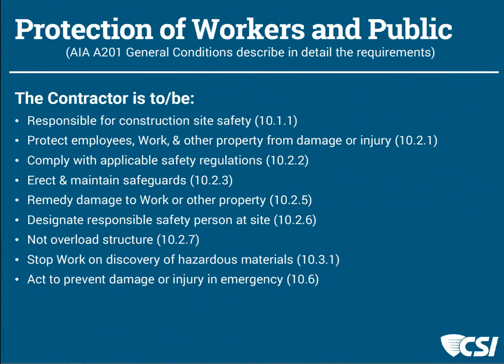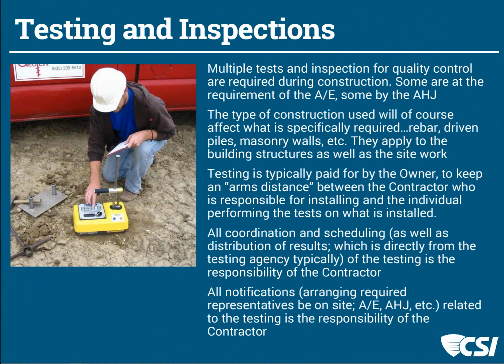Let's take a look at the next slide, Matthew, and touch for a minute on another piece, a little backward look about executing the work on the site, and those are the testing and inspection agencies that might be involved. Our specifications may require, materials or products may require, local municipalities may require, or authorities having jurisdiction may require a series of different kinds of tests. It's the contractor's obligation to coordinate for those to happen at the appropriate time, whether it's in the building or